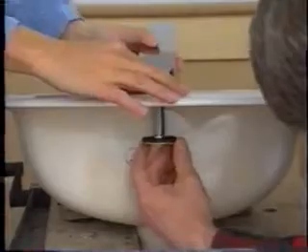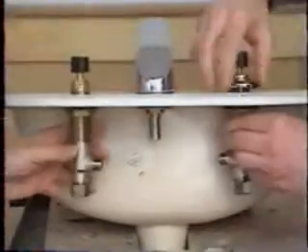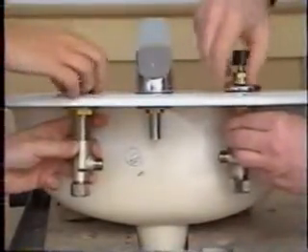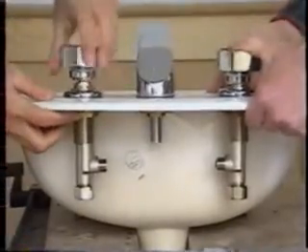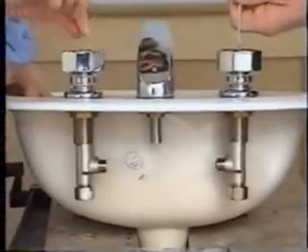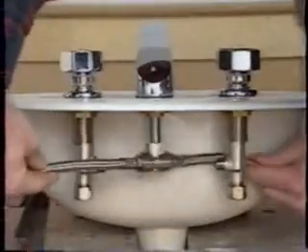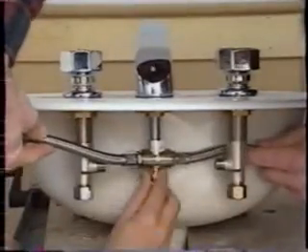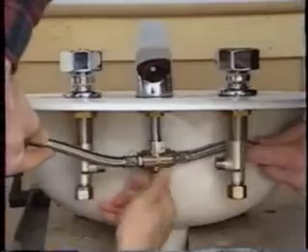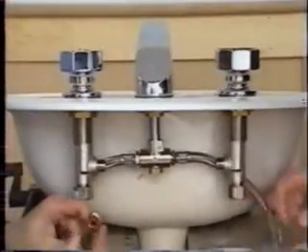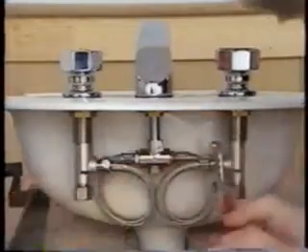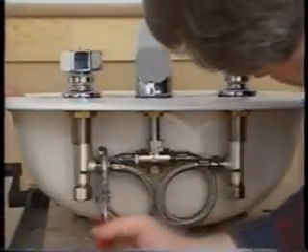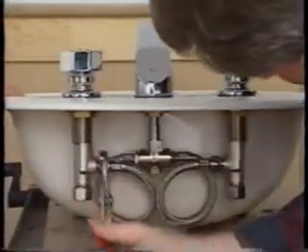First, we secure the spout and the hot and cold water valves. Handles go over the adapters on each valve stem, and they're secured with screws. We connect the supply hoses to the spout through the T in the middle, and coupling nuts secure the hoses to the hot and cold valves. Now, installation varies between models, so be sure to follow instructions that come with your assembly.